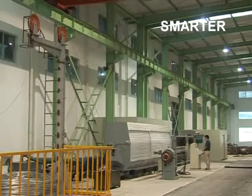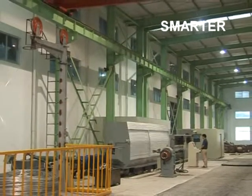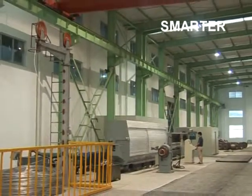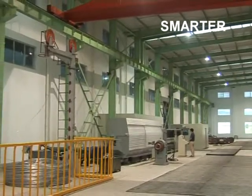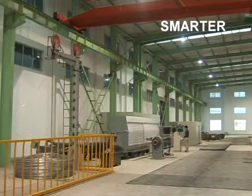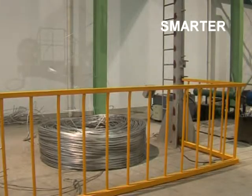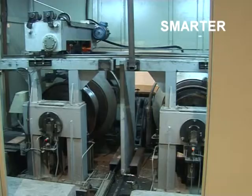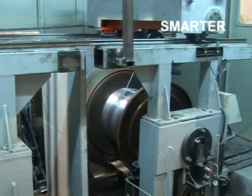LSAF 450 7-dies non-slip aluminum rod breakdown machine was a new product designed and developed by ourselves in 2007, which was first innovated in China and has been successfully used in customers' plants. The equipment's main usage is drawing 9.5 mm aluminum alloy rod to a fine diameter of 3.6 to 6 mm round-shaped wire or same-section irregular-shaped wire.